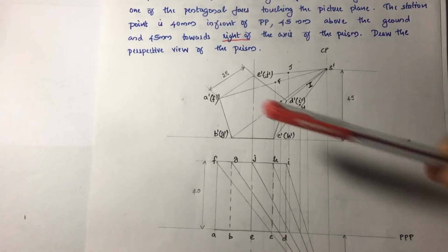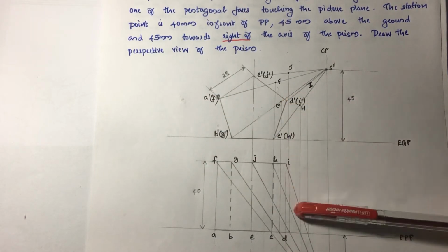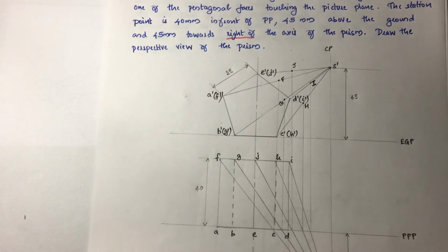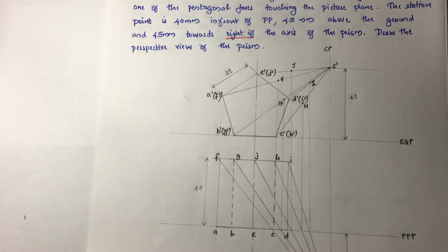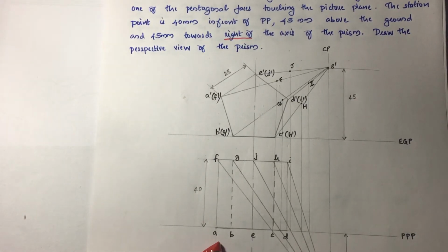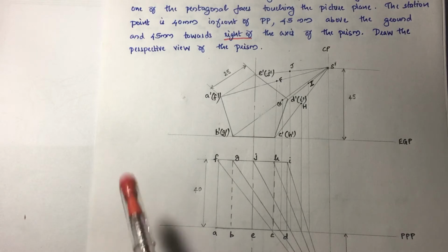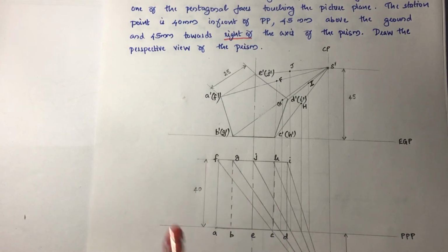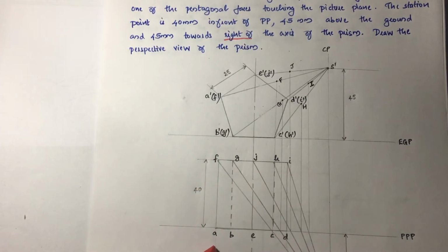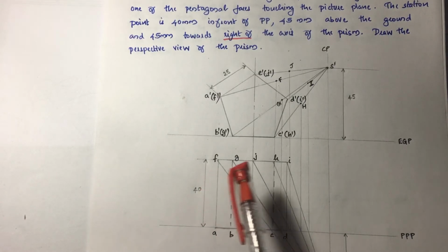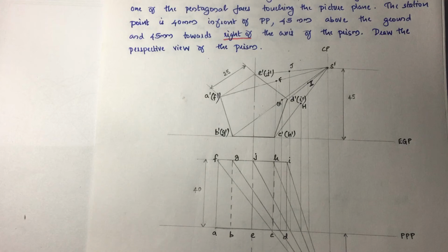You have to project from this pentagon's outside edges and complete the rectangle. And as you do in the case of orthographic projections, you have to mark the visible edges, which is the one that is not given inside brackets at the bottom face, and the one given in brackets in the top face. So correspondingly A, B, C, D and E come here, and F, G, I, J, H come here.